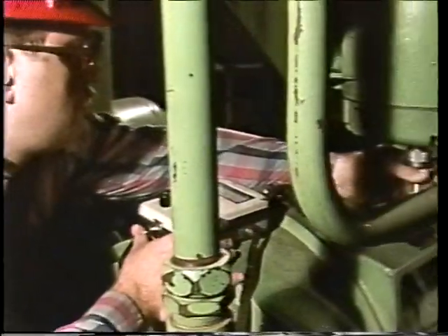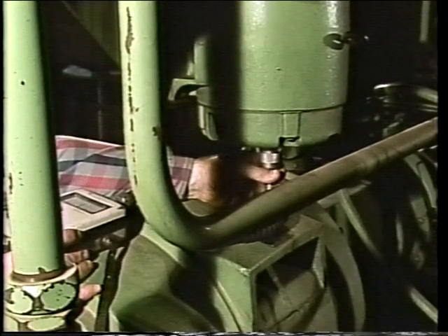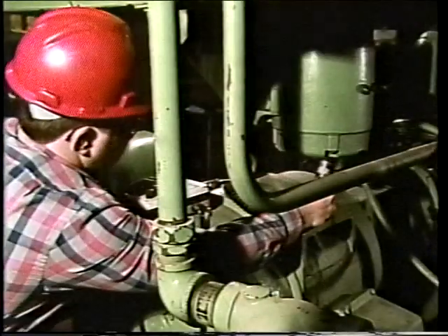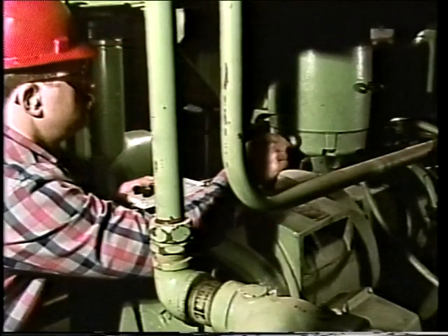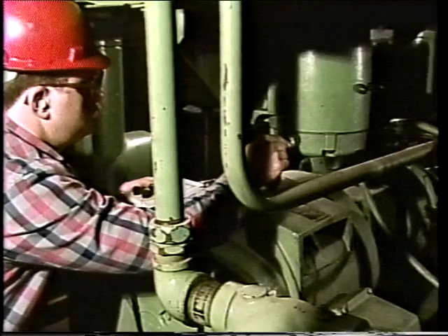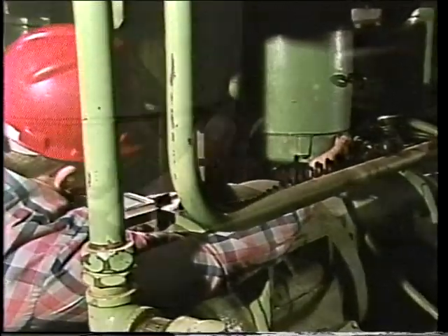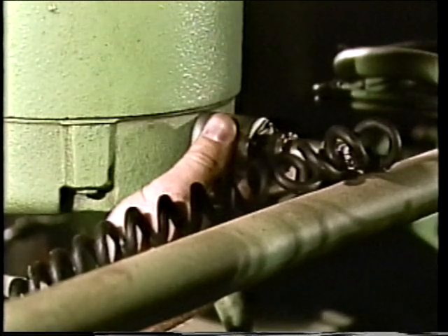On a machine equipped with a vertical shaft, the readings are still taken from 3 directions. One check is made parallel to the center line of the shaft, another is made perpendicular to the center line in the horizontal direction, and the final check is also made perpendicular to the center line in the horizontal direction, but at a 90-degree angle from the second measurement.